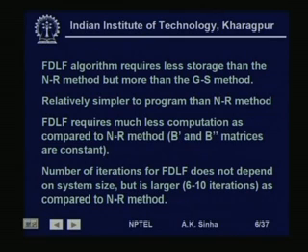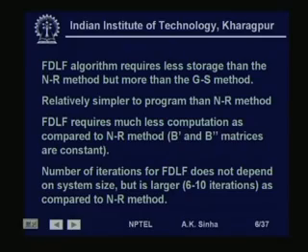The algorithm is simpler to program than the Newton-Raphson method. Again, this is mainly because the Jacobian element calculation is no longer involved here. The matrices B dash and B double dash are basically the susceptances of the Y bus matrix, the susceptance elements of the Y bus matrix, and therefore, much simpler to compute.